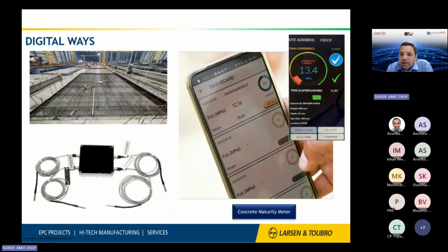And every minute, every 10 minutes, it will update saying now your concrete has gained 6 MPa, 6.6 MPa, 7 MPa, where our engineers now have that ability where you give the design strength. As soon as the panel hits 15 MPa, you can lift it, take it, store it, and start your next activity. Right? Cast in place is slightly different.